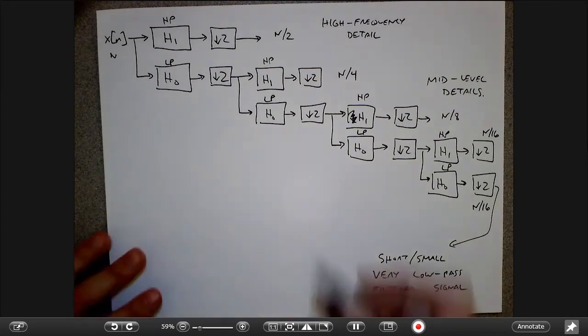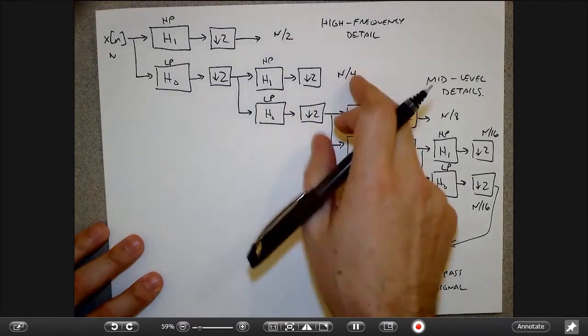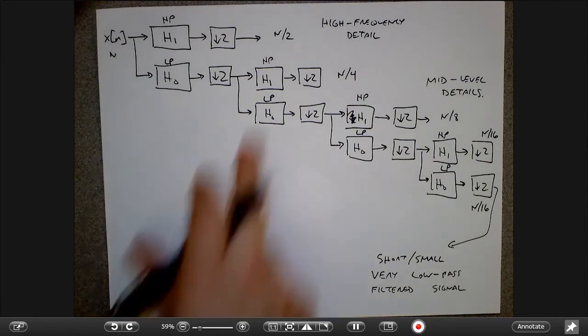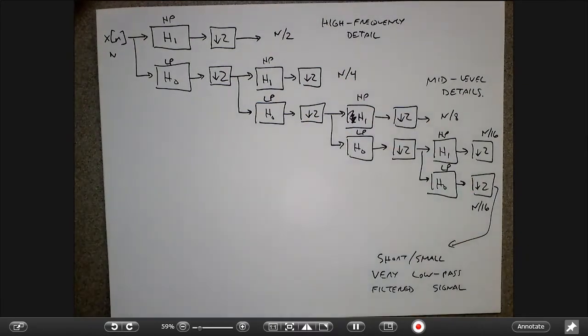So the idea would be that I would put all these through some sort of a compression algorithm, which is related to the quantization stuff we talked about last week, where I would quantize these coefficients at various levels, and that would hopefully make my signal a lot more compact, so that when I reconstructed it on the other side from these quantized coefficients, I would get something that looked pretty much like the original signal, but would use a lot fewer bits, right?